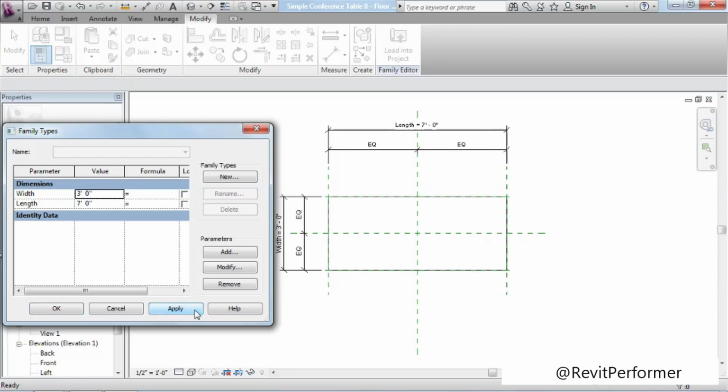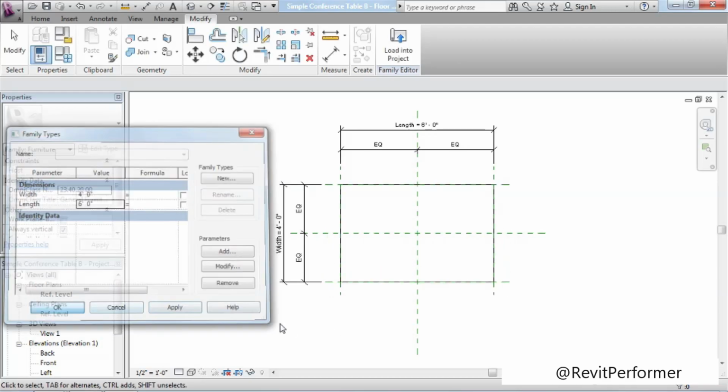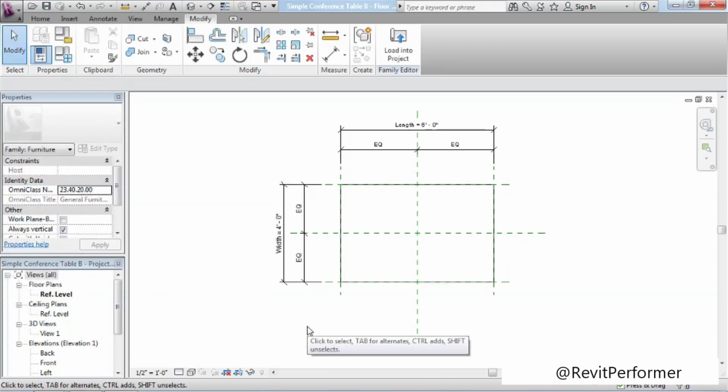You may be a little surprised to see that the form actually adjusts, even though we didn't constrain the sketch, right? We did not click the little padlock icons, and the sketch, therefore, was not locked to the reference planes, but yet somehow Revit is assuming that we want that behavior anyway. Why is it doing that? Where is that assumption coming from? I'd like to talk about a concept called automatic sketch dimensions.